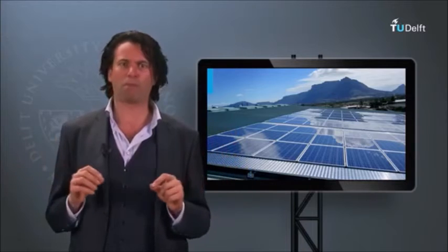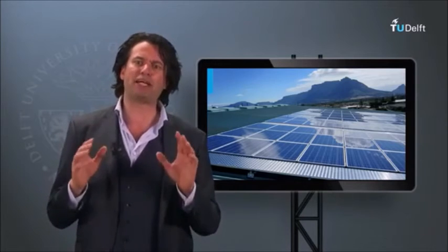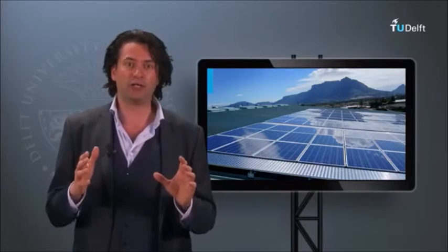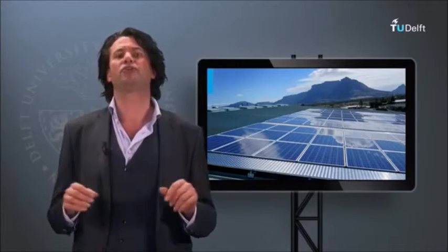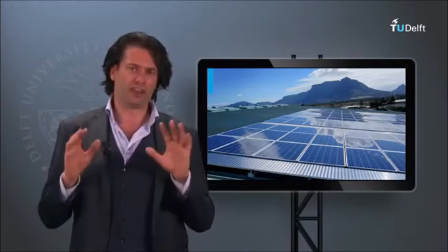Whether or not the grid operator pays you back for this excess depends on the net metering related policy of the electric utility you are connected to. If your grid operator pays you back for every watt of PV power you pump into the grid, it might look beneficial to oversize your PV system. But then the decision would depend on the system cost and the expected system yields, which in turn depend on the irradiance of the place, module level effects, etc. Thus, there could be quite some optimization that could be done purely at an economical level.